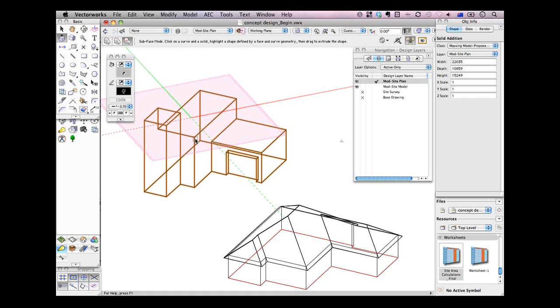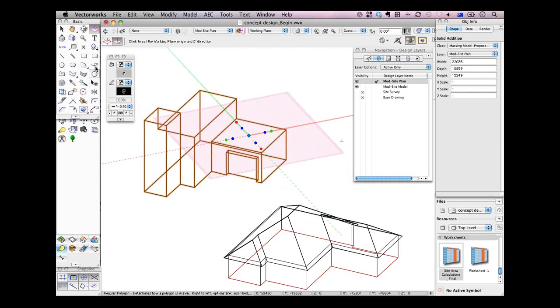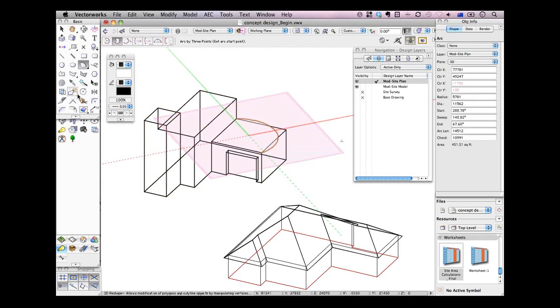Well, the push-pull tool tends to pull planar objects. So they tend to be extruded type objects, but they don't have to be rectangular objects if you don't want. So let's put a working plane on there, and I'll do a curvy shape on there. So push-pull tool.